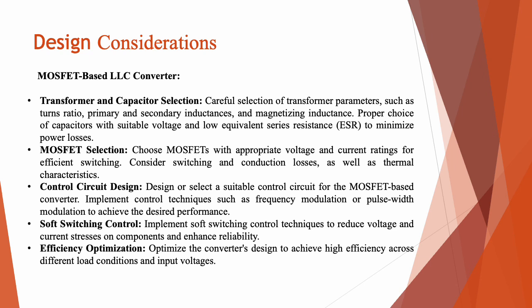For the control design, we have implemented techniques such as frequency modulation or pulse width modulation to achieve the desired performance, and soft switching control techniques are implemented to reduce voltage and current stresses on components and enhance reliability. The optimization of the converter's design is done to achieve high efficiency across different load conditions and input voltages.